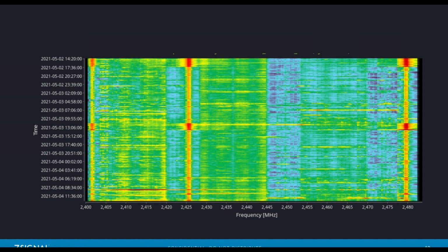Yeah, and Bluetooth has a feature where it tries to just use the portion of the band that's not being utilized. So it tries to be polite, but Wi-Fi is so spectrum hungry. Look at all the spectrum that we're using. If we're using those 3 channels, we're using 60 megahertz of spectrum, and that doesn't leave much for Bluetooth. So it can only do so much to avoid interference and still get the job done. That's right. They're going to wind up stomping on each other eventually, depending upon the environment. And that's what we're looking for.